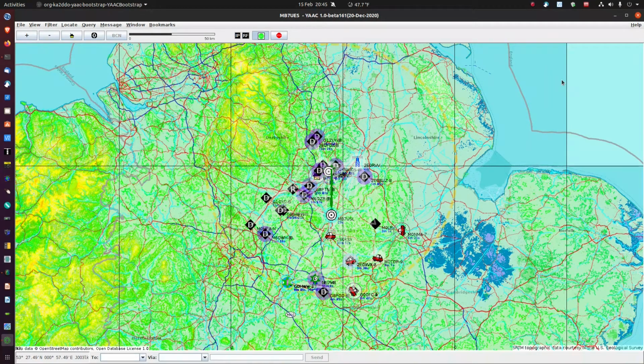In this demonstration, I'm going to show you how to use something called APRS, or Automatic Packet Reporting System, for amateur radio. This is a move on from the old packet stations you've seen already, and this uses packet but with a different purpose. So the system setup is essentially the same, some sort of computer, a TNC and a radio, and the way this works is, as well as transmitting the message, it transmits coordinates from a GPS device, or if you're a stationary station, you can just put your coordinates in and leave it at that.